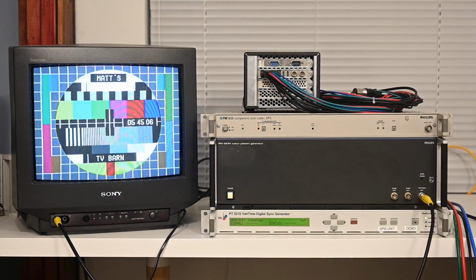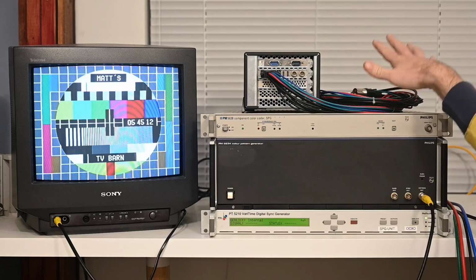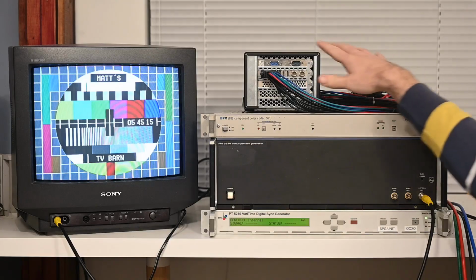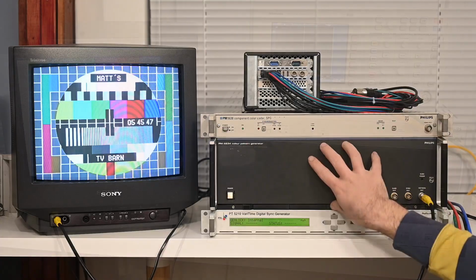Now, our video sources in question are firstly going to be everybody's favorite, the PM5534, and secondly, we're going to be using this AJA Kona Video I/O, which is in this Thunderbolt enclosure here. Now, one annoying limitation I discovered with this device when I was making this video is that the phase of the color subcarrier on the composite output is fixed, which is not ideal, and I would say probably rules it out for serious analog studio use. To get around this problem, we're going to be using a professional PAL coder, this PM5638. We'll be feeding it with an RGB signal from the Kona, and then we will take our PAL composite from this unit and mix it with the 5534.